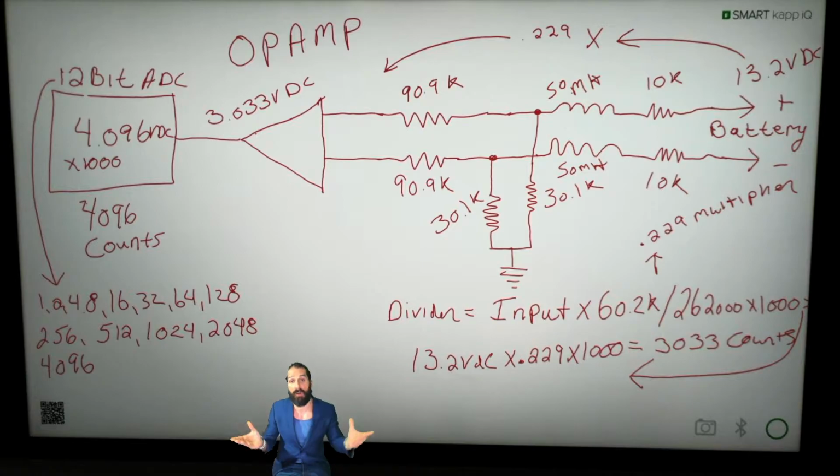If we have a 16-bit analog to digital converter, generally you can scale from 0 to 20 volts. Now, what this is doing is increasing your resolution, right? So if you have an input signal and you have to scale it way down, you're reducing your resolution, especially when it's inherently input into your calibration constant. So you must absolutely understand the scaling factor within analog to digital circuitry.